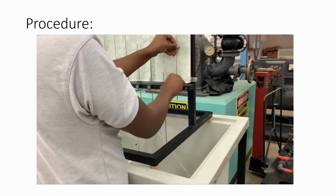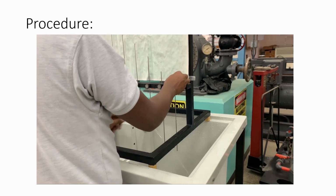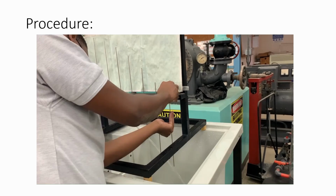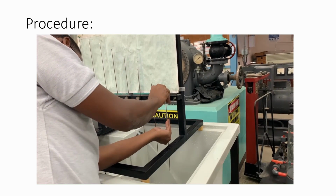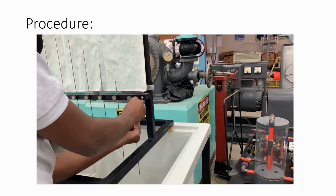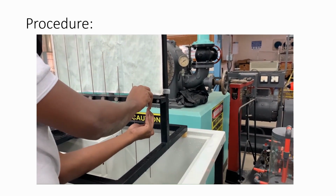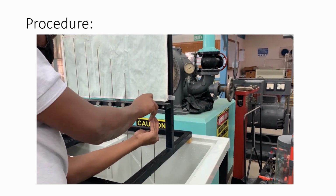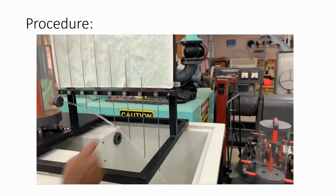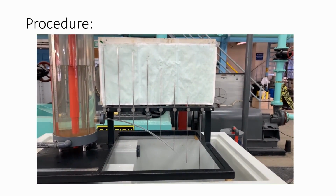What is important to note here is that the final probe, the eighth probe, would be unable to touch the jet trajectory, and this is a limitation of the apparatus. So in your results, you will see that the eighth probe for this specific height of 250 millimeters would have this noted in the results.